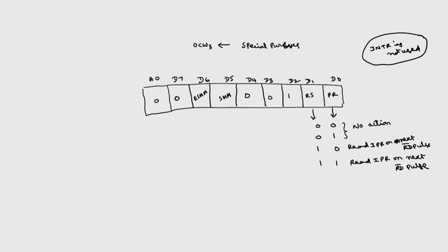So this 8259 will send INTR to the microprocessor, then the microprocessor acknowledges through INTA bar, thereby the type of interrupt will be specified, meaning the type of call instruction. After that the particular interrupt will be served.